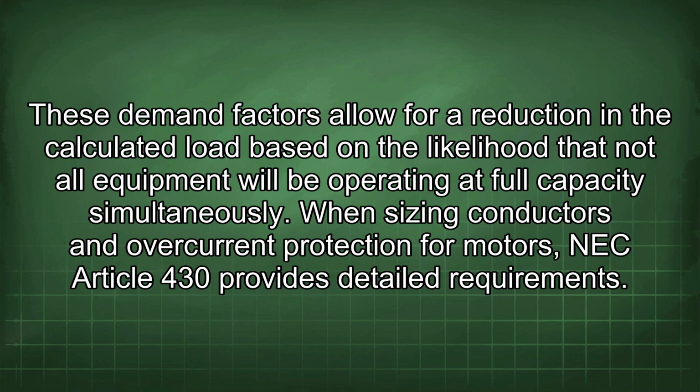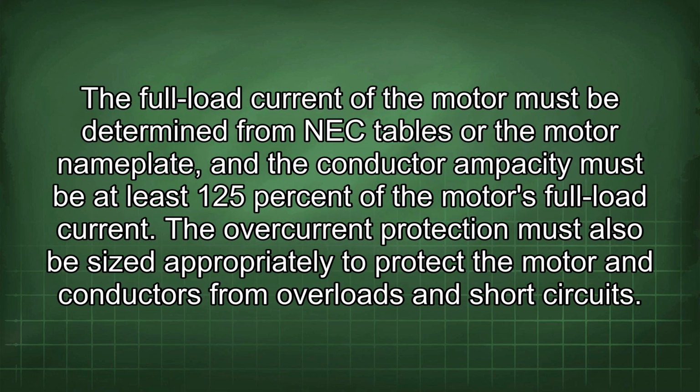When sizing conductors and overcurrent protection for motors, NEC Article 430 provides detailed requirements. The full load current of the motor must be determined from NEC tables or the motor nameplate, and the conductor ampacity must be at least 125% of the motor's full load current.